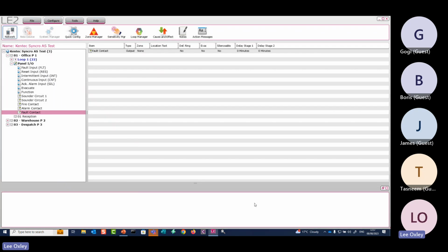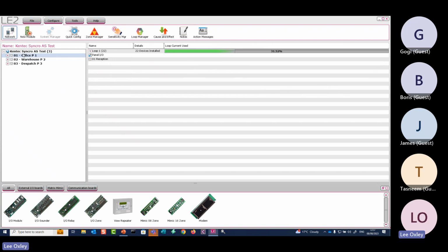So you can see that all those I'm going through are connections actually in the panel itself, on the main motherboard itself. Okay, that's what these panel inputs and outputs are. They're in the panel. You get them with the panel all the time. You can tweak these depending on your particular site. Once you've tweaked these, once you've labeled them and changed their properties, you can then upload this config file. I'd upload it back to all 3 panels at this point if I made some changes like that.